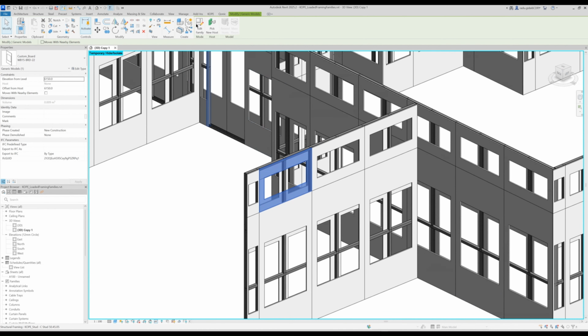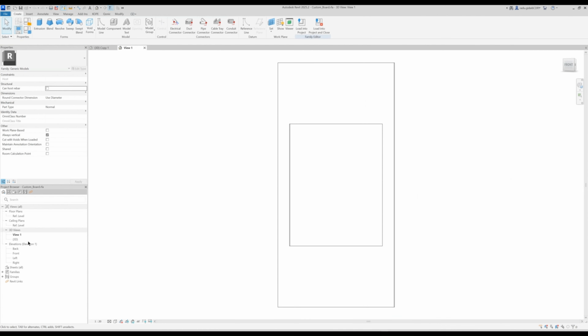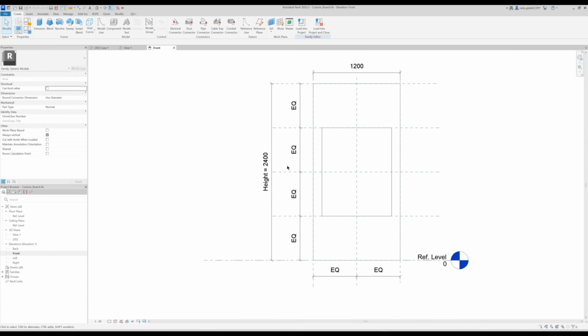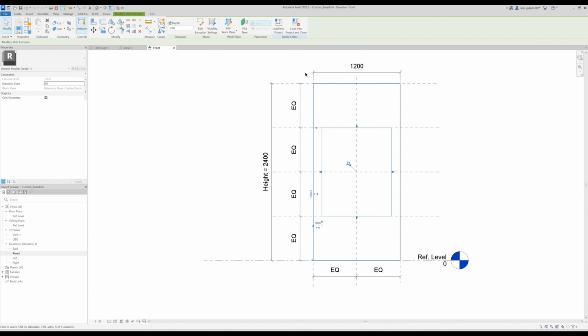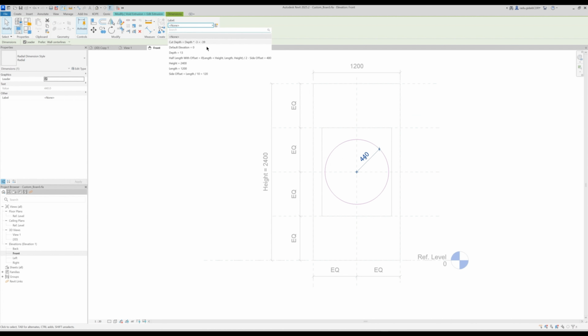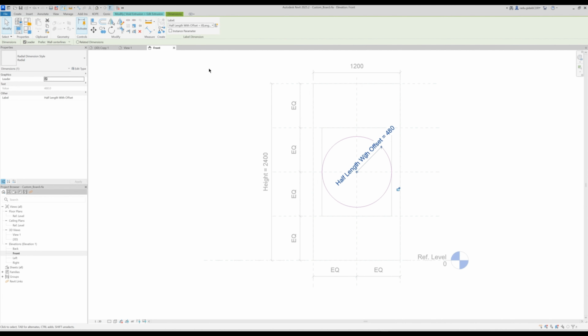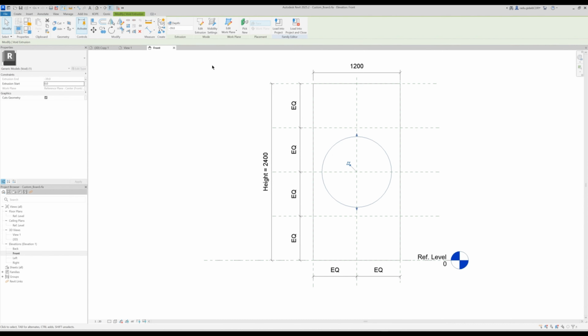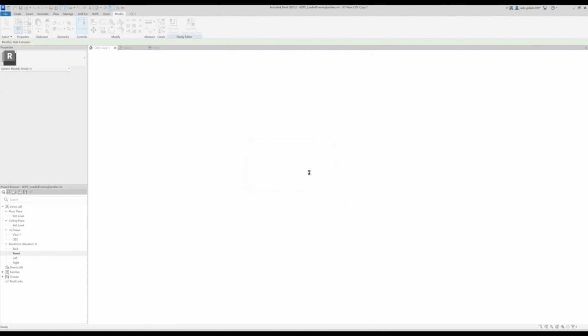And what we're seeing on the screen here is that this is a normal Revit family. You can go in, edit family, you can change this opening, for example, that we had in this family, and we will make it parametric. So we'll tie that to a type parameter. We'll load it back into the Revit project, and you'll see all of the instances and all of the types already update.